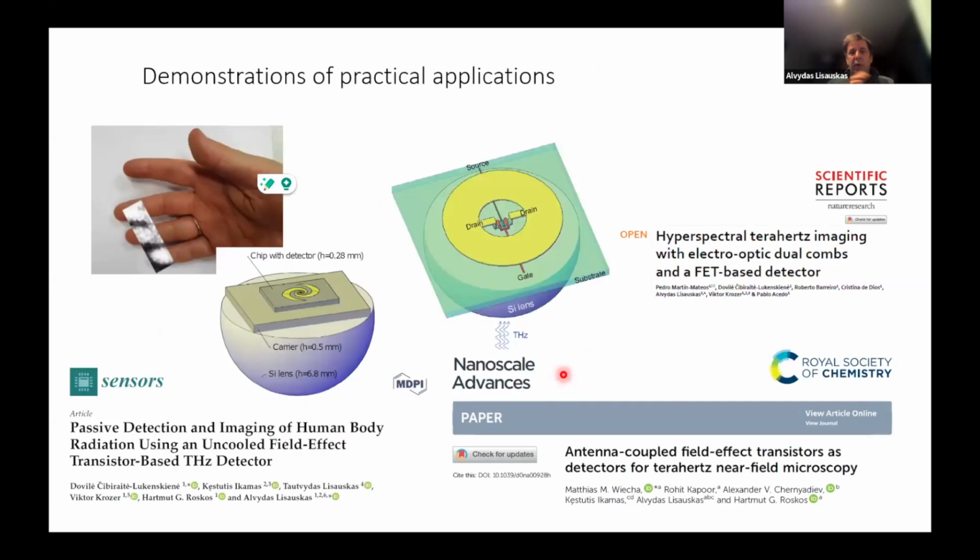And so in cooperation with different teams, we have created practical applications. This is approximately how one device would look. One has a spiral antenna, just placed on a hyperhemispherical lens, and then the radiation couples from the substrate side. This is the most usual case to couple radiation efficiently out of free space into a device. The sizes here are absolutely not comparable, because the antenna would be really below a millimeter, with the lens being tens of millimeters. The diameter would usually be 12 millimeters.